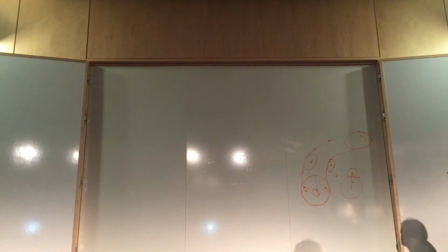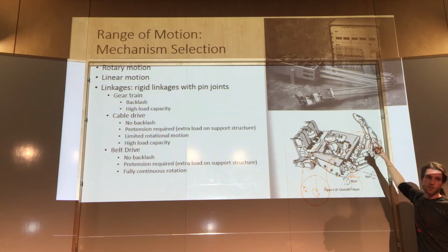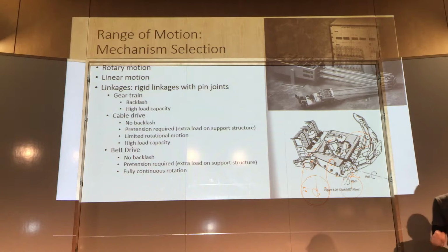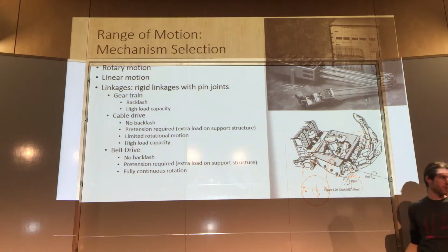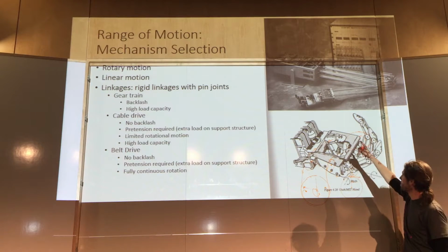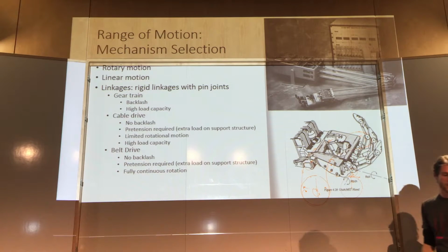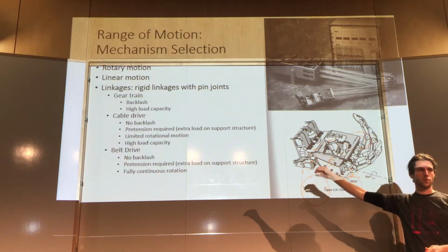Whatever. You can just imagine running all those cables for that hand all over the place, every one of those pulleys, you've got to try to string it around. It could be a real issue, and you have to terminate every cable. Every time that cable ends and applies torque, there's a special termination you have to put on there. You have to crimp that on. That could be a real pain. So you've got to be careful with those. There's a lot of overhead that comes along with them. But it's used a lot in robotic hands because you put all the gearboxes down at the base, and then you just run lightweight cables all the way up to the ends.